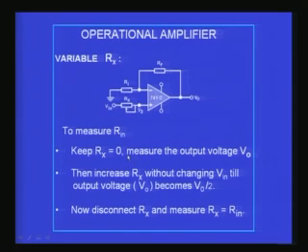Now whatever is the input voltage, it will be multiplied by the gain and I will get the output. If the output voltage has become half of the previous value, that obviously means that V3 has become half of Vin. The voltage at point V3 has become half of the voltage at point Vin. That is what we understand when we get half the voltage. When will this happen? When will a voltage divide equally? It will happen only if I have two resistors which are of equal value.